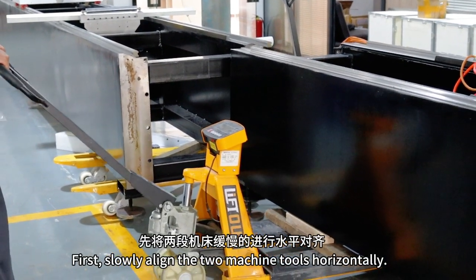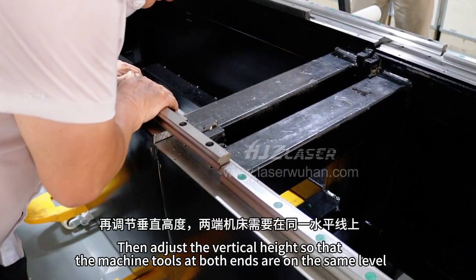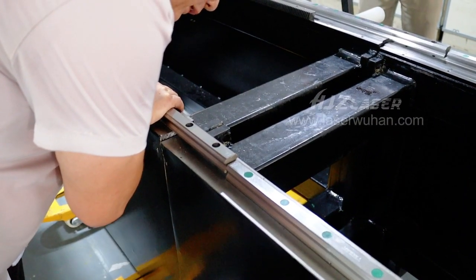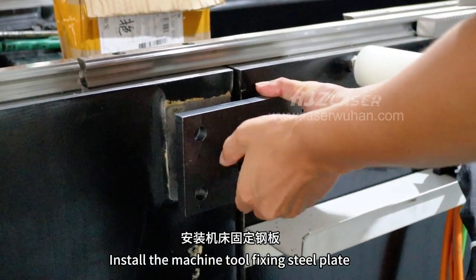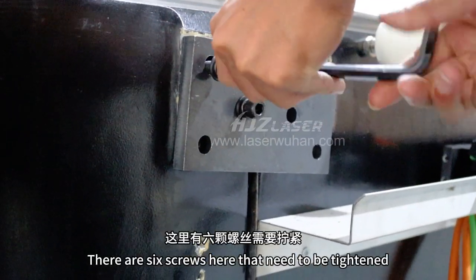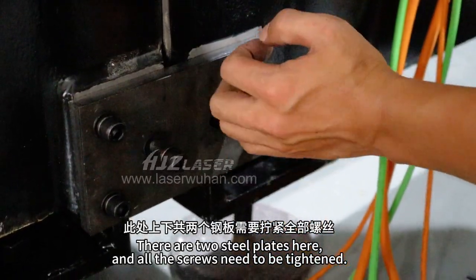First, slowly align the 2 machine tools horizontally. Then adjust the vertical height so that the machine tools at both ends are on the same level. Install the machine tool fixing steel plate. There are 6 screws here that need to be tightened. There are 2 steel plates here, and all the screws need to be tightened.